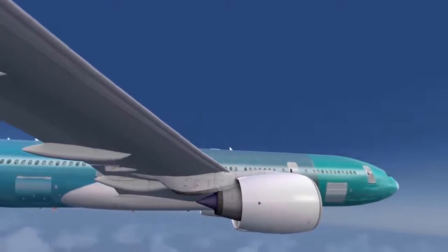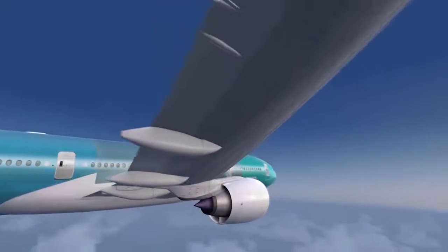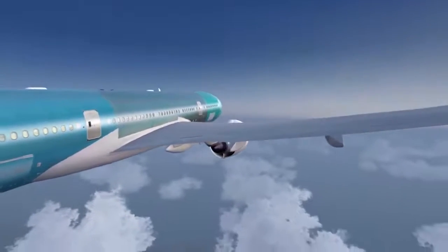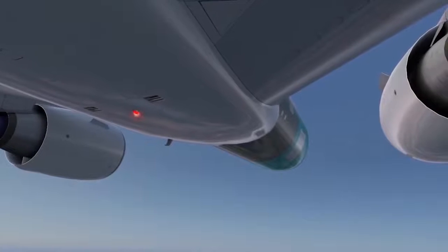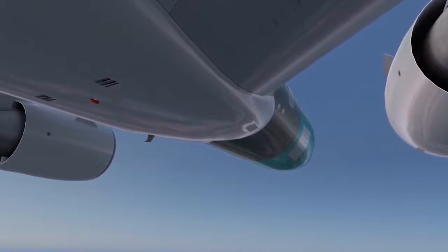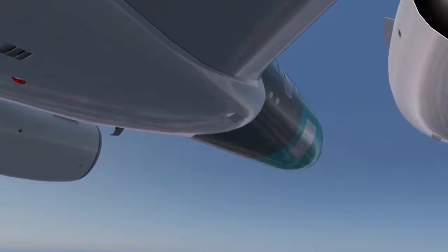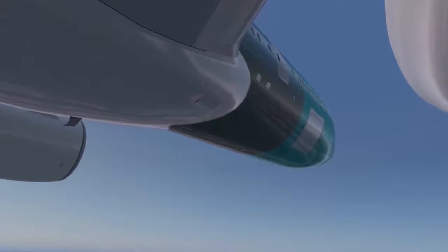If there is any fault in the recirculation fans, the air condition reset switch can also restart them. The air conditioning packs also protect themselves from faults whenever there are certain system malfunctions. Pack control in this case automatically enters a standby cooling mode in order to back up normal mode, instead of fully shutting off. If one pack is normal and the other is in standby cooling mode, the standby mode pack shuts off at lower altitude where outside air temperature is not as cold, so as to be uncomfortable for passengers and crew.